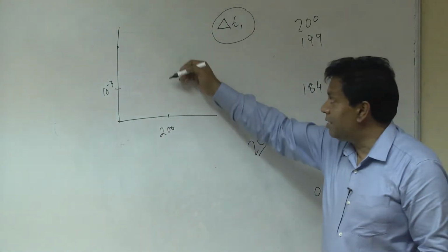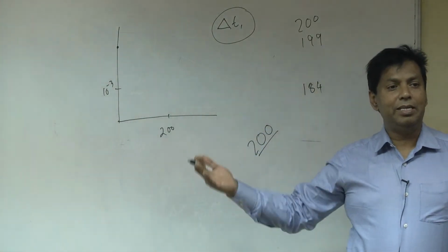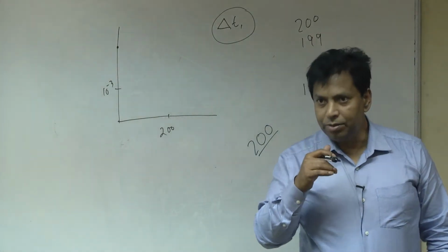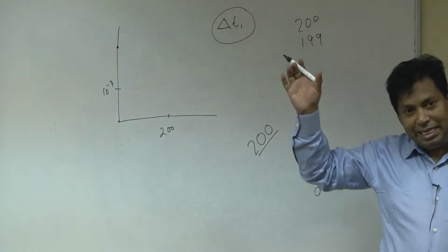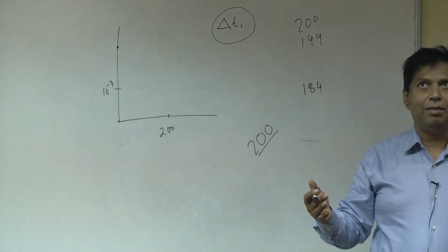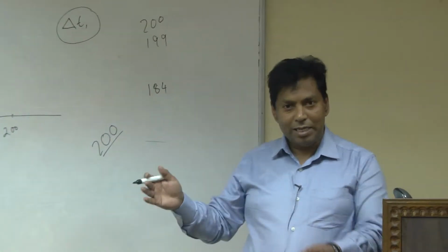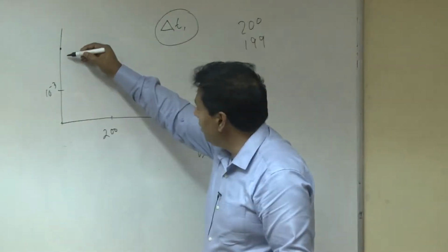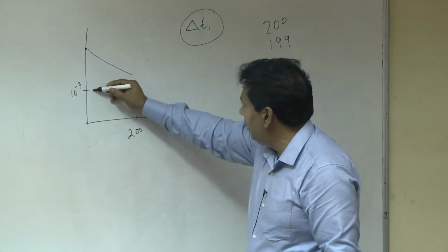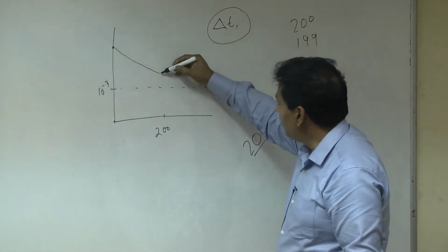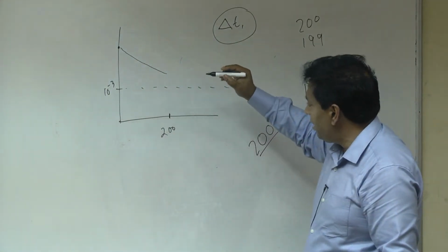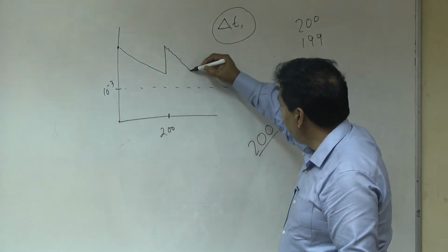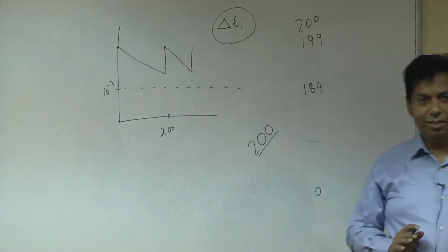So that means the time step is called the outer iteration. How many time steps are we solving? 3000. So that is the outer iteration, 3000. And each time step we have about 20 or 25 iterations. That is called inner iteration. So two kinds of iterations. You have to be very careful that sometimes it is coming here and not coming down to here. That should be the convergence line. You told it the maximum iteration is 200, but it does not come down here, then it goes back up and then comes here. It means it is not actually converged. So you have to check this.